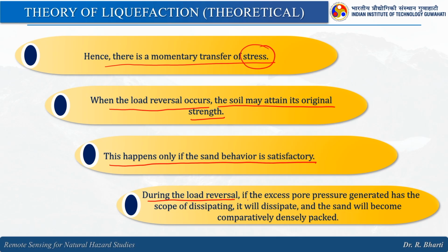During the load reversal, if the excess pore pressure generated has the scope of dissipating, it will dissipate and the sand will become comparatively densely packed. So, this is after the load reversal. Again it is getting densely packed.